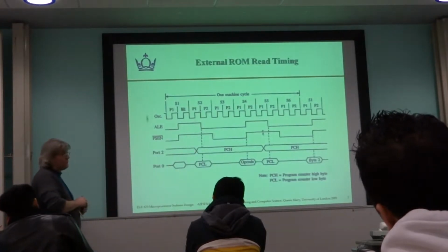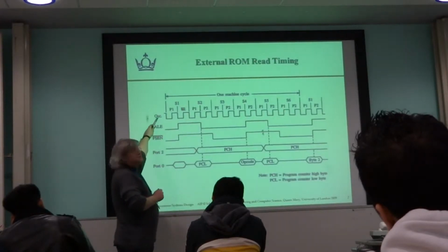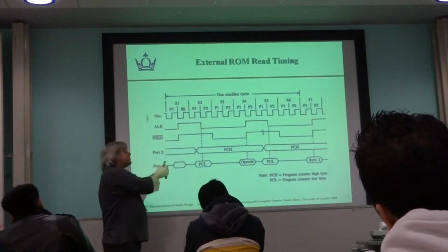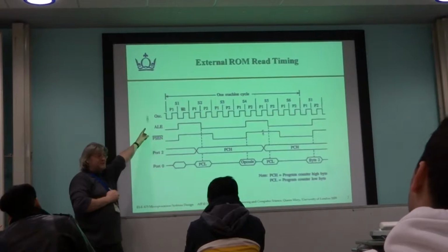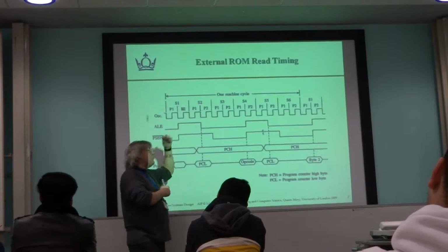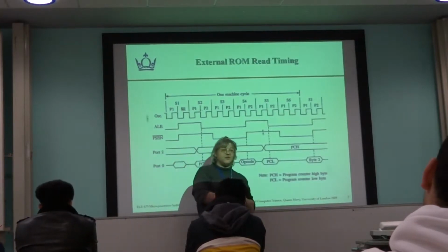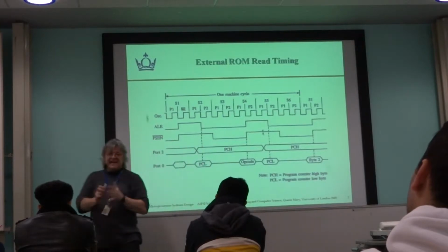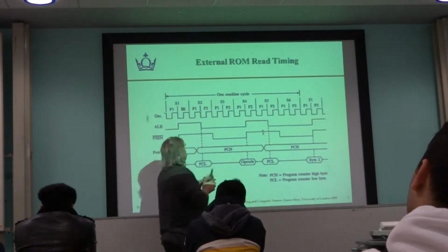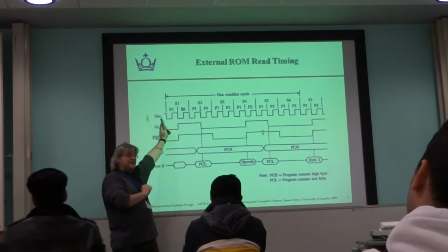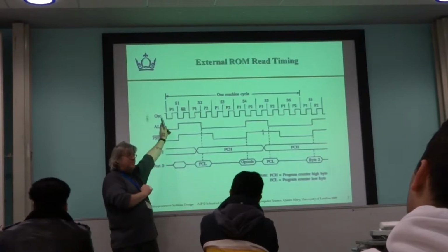For example, if I'm using an 8 megahertz crystal, can I still achieve the same? You can't. If you change the crystal speed, you will change the speed that everything happens here. And this is a crucial point: if you choose to have a 1 megahertz crystal, basically everything slows down. Everything takes longer. So if you want your microprocessor to, I don't know, control some video display, and it has to achieve its task within a certain time, that might put a limit on what clock frequency you need to use. So you need to pick the right kind of frequency, one that's fast enough for your job.